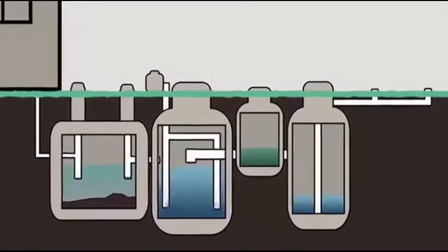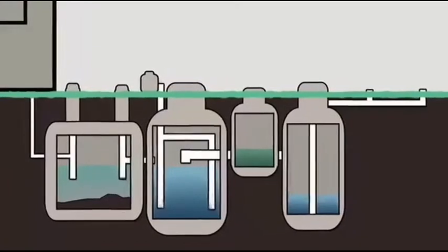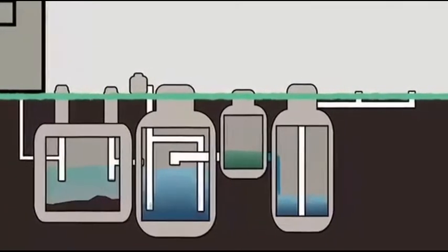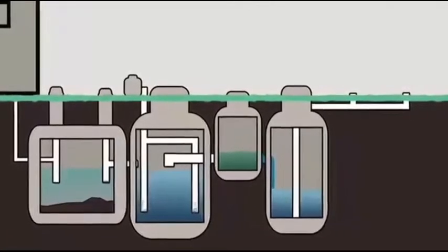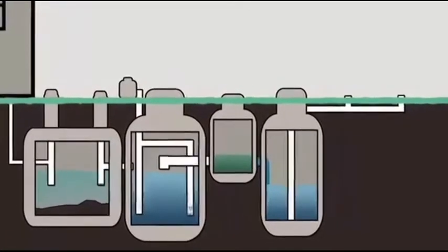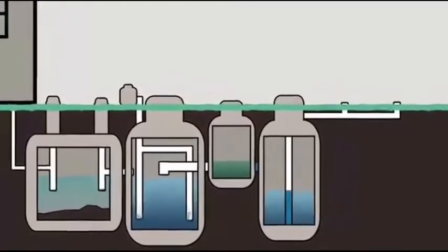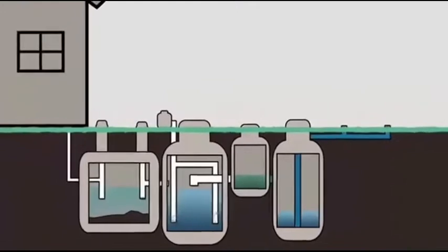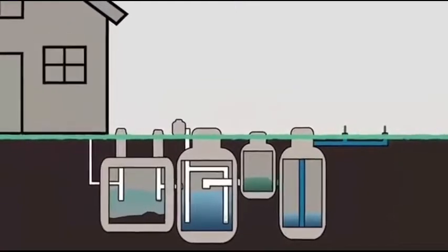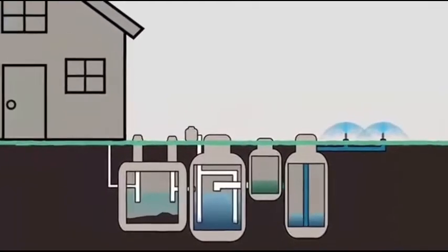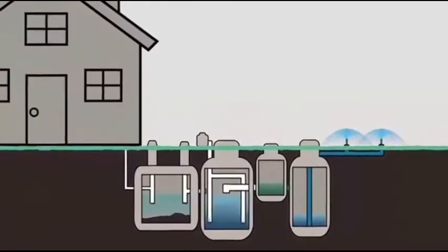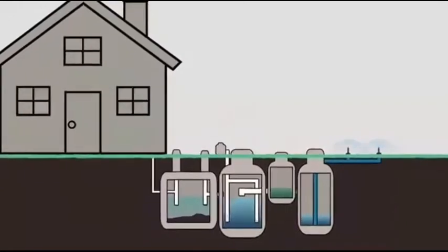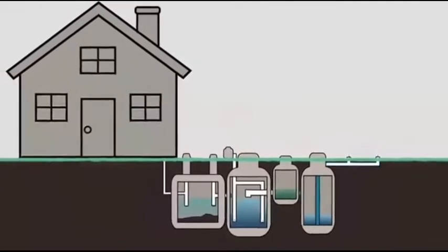Aerobic treatment units can be used to remove substantial amounts of BOD5 and TSS that are not removed by simply sedimentation in a conventional septic system. The biological process also involves the nitrification of ammonia in the wastewater and the reduction of pathogenic organisms. Nitrification is the breakdown of ammonia to nitrate by microorganisms in aerobic conditions.